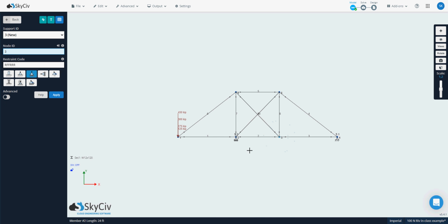If you do add additional supports along a truss, it's probably a good idea to put these as rollers, because if you start putting them as pins, the truss is not going to behave very well in terms of allowing it to expand and contract and actually utilize the members. What you'll get is arching action. Let's say you got a pin here and you got a pin here.